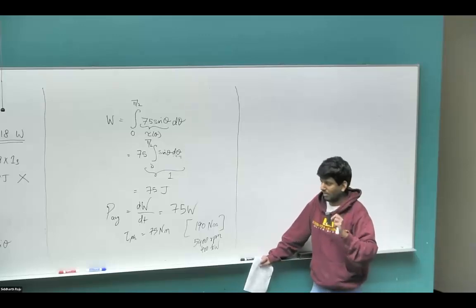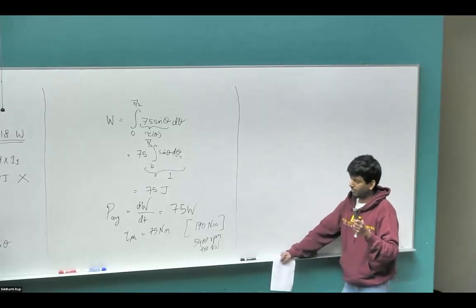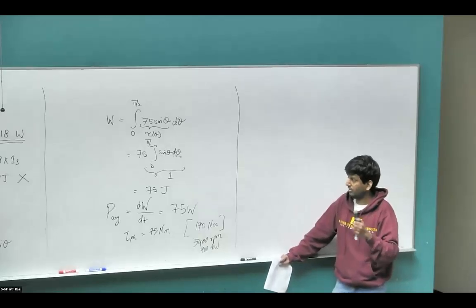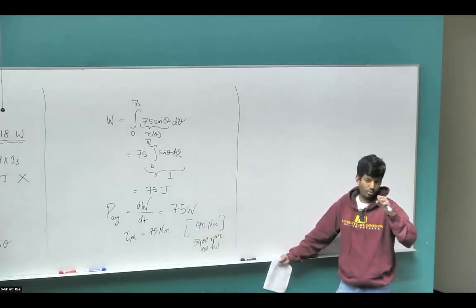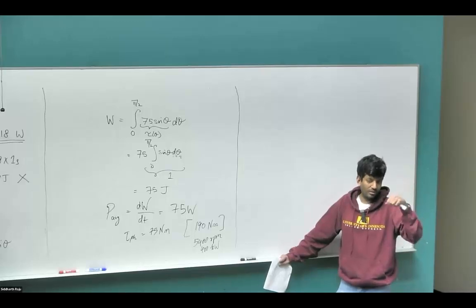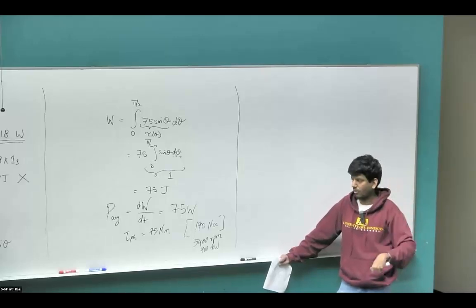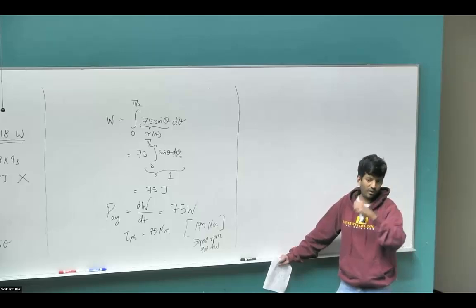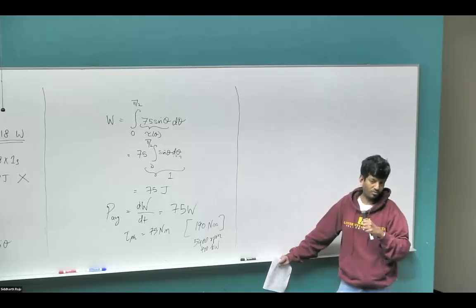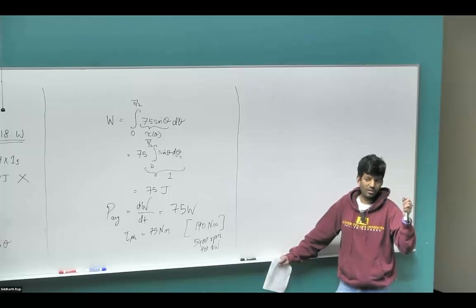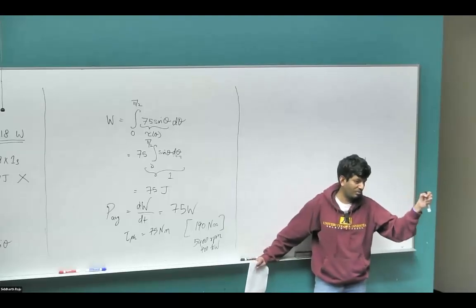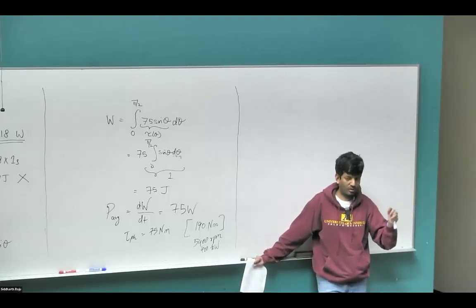So in the transient temporary period, a hydroelectric power plant, which is somewhat faster to respond to these transient power demands, the energy stored in the inertia of the generator rotating in the hydroelectric power plant is what is going to provide the additional energy required on the load side. If the inertial energy is not there, then the whole grid would collapse, because there is additional energy needed, but there is nothing on the generation side providing it. So the system would start to collapse. So this is extremely critical in traditional power systems. We have this inertial energy coming from these rotational generators.